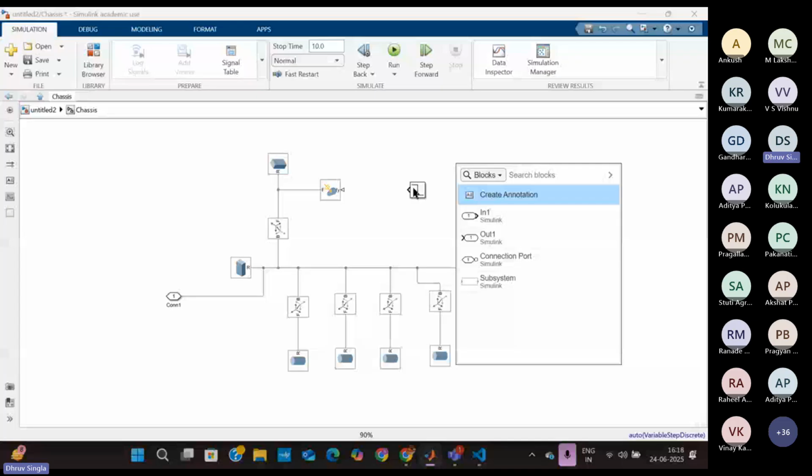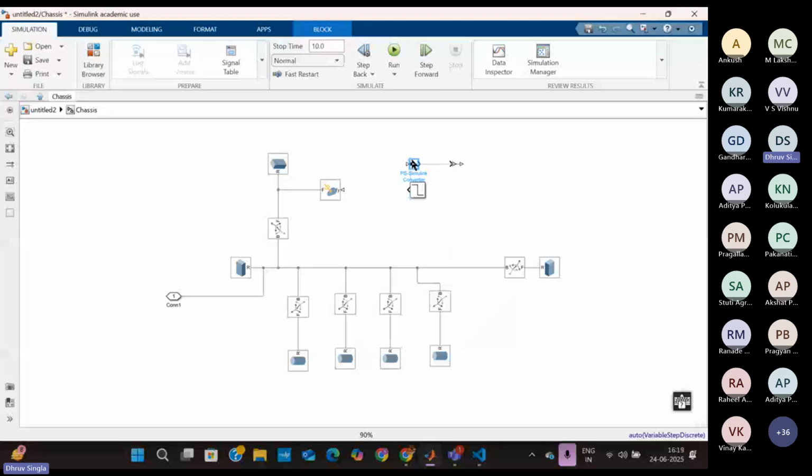So we have these two types of converters. This one is Simulink to PS, and the other is the vice versa, the PS to Simulink converter. So let's put this one here, Simulink to PS. As I said earlier, I need the Simulink signal coming from the step to be converted to a physical signal to be given to the force block. So I rotate it and connect it with this, and another end to this. Just for the time being, we'll come to its use later on. So I now have the force being applied by the signal to the third plate. Let's see how it will look in the simulation window.